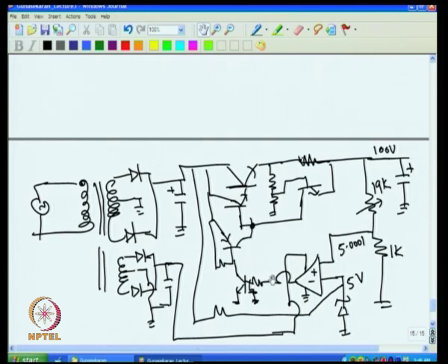So an increase in voltage increases this voltage and increases that voltage at this point. That means the increase in voltage here will increase here, and then that will increase this and further increase this. So it will go into positive feedback. So if I use this circuit, all that I do is change this: instead of minus, I put plus minus there and then put plus here.